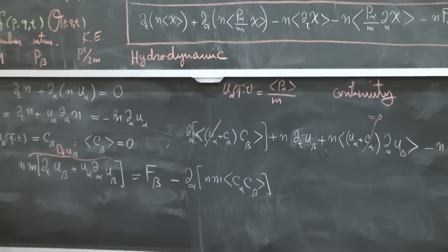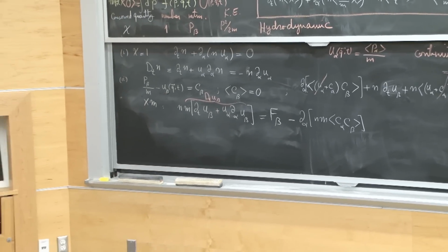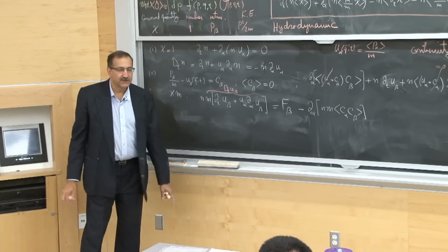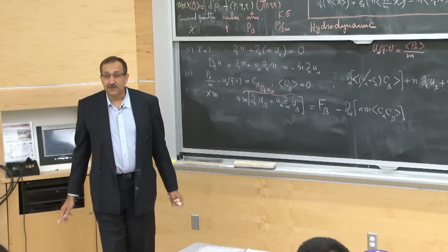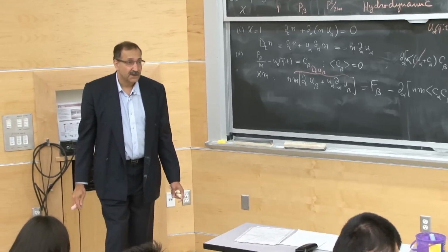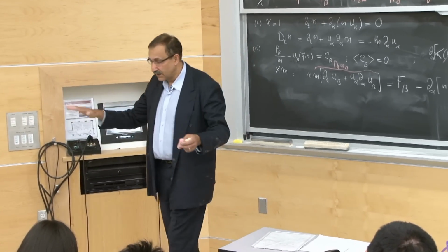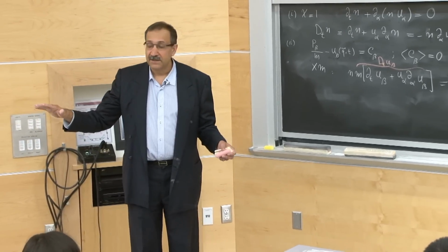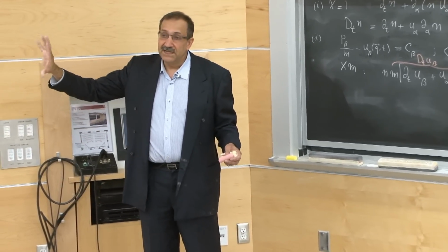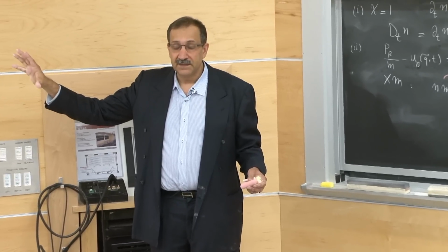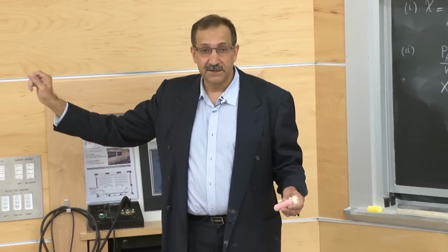Okay? So what happened here? Isn't force just the mass times acceleration? Well, as long as you include all forces involved. So if you imagine that this room is totally stationary air, and I heat one corner here, then the particles here will start to move more rapidly. There will be more pressure here because pressure is proportional to temperature, if you like. There will be more pressure here, less pressure there. The difference in pressure will drive the flow. There will be an additional force.